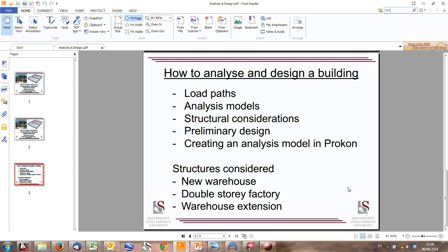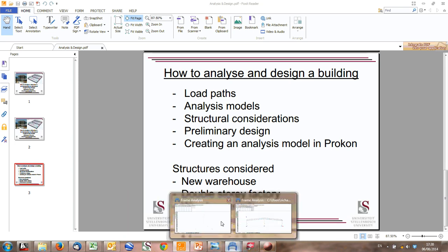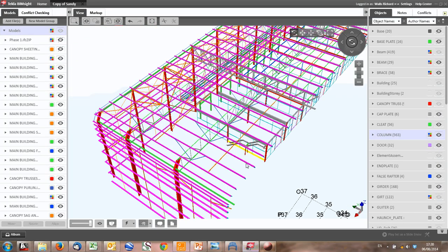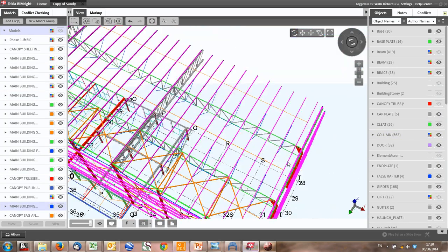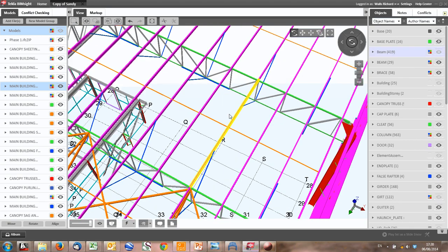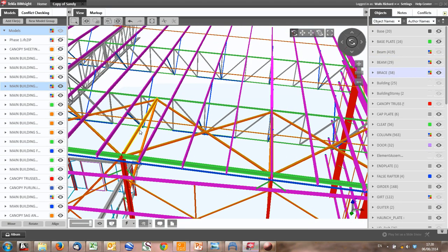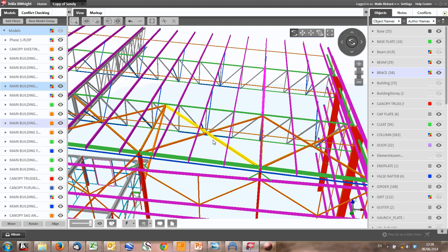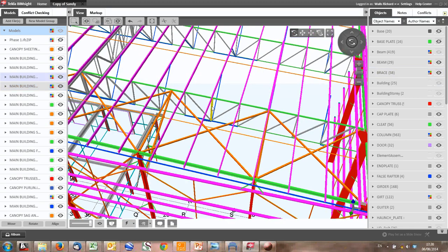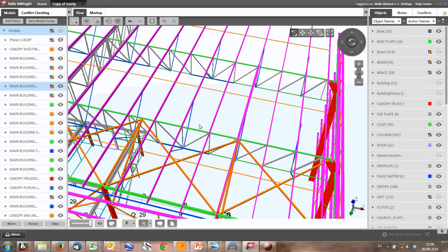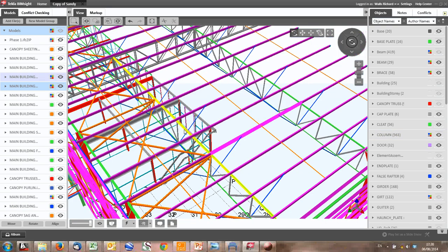As let's say now we model this. Let's go back to our 3D model. Imagine you model this in 3D. If you don't model these purlins correctly, it might assume that the purlins act with the roof bracing. Instead of the roof bracing obtaining load, it goes down purlins, and you might add stiffness to the structure that doesn't necessarily exist.